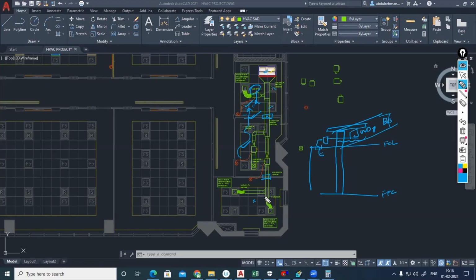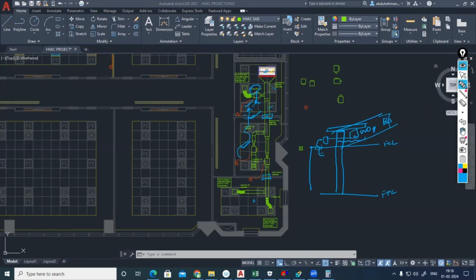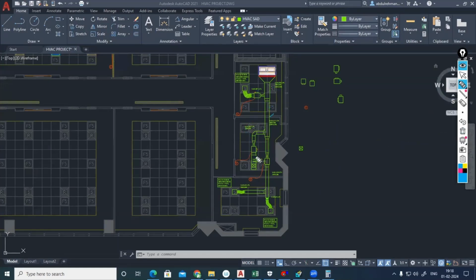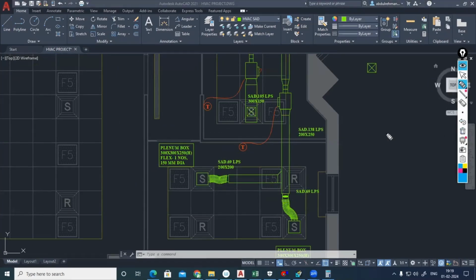Wall opening. The dimension of wall opening with the 2.5 meter per second, you can size it. 2.5 meter per second, continuity equation you can apply and you can size it. Otherwise, the same supplier duct you can maintain. But if the return wall opening, when you are sizing, if the return velocity is minimum like 2.5 meter per second, that will be good, or less than 2.5 meter per second, that will be good. It will not create any noise there. Okay. So for example, discussion room 3, I have to arrange a wall opening for return above the false ceiling.